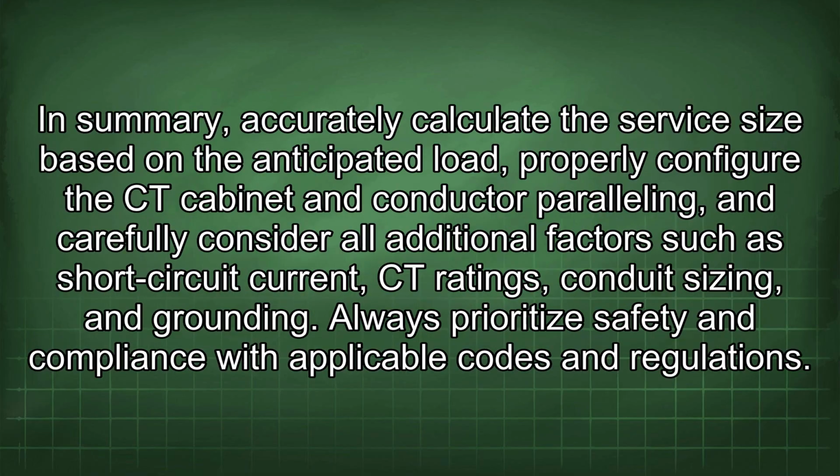In summary, accurately calculate the service size based on the anticipated load, properly configure the CT cabinet and conductor paralleling, and carefully consider all additional factors such as short circuit current, CT ratings, conduit sizing, and grounding. Always prioritize safety and compliance with applicable codes and regulations.